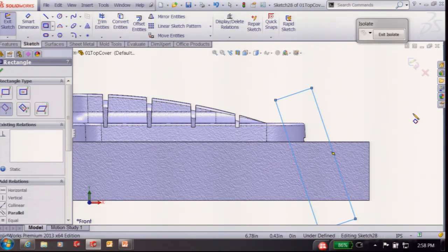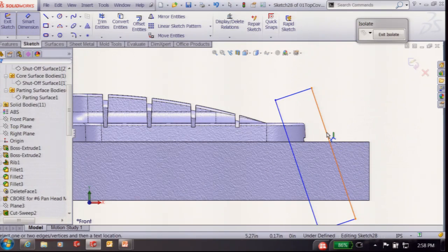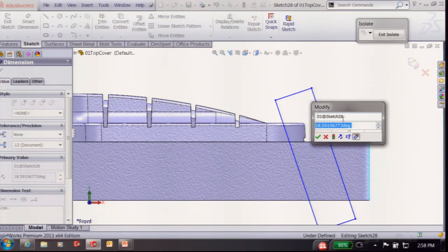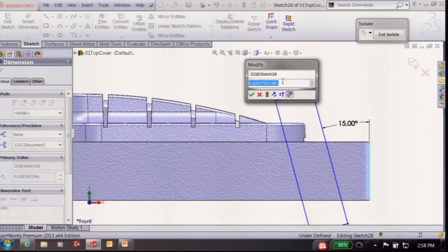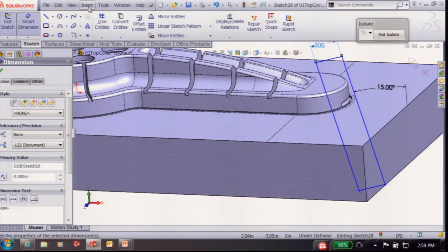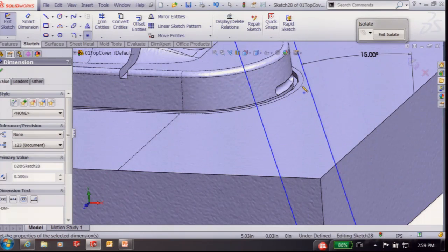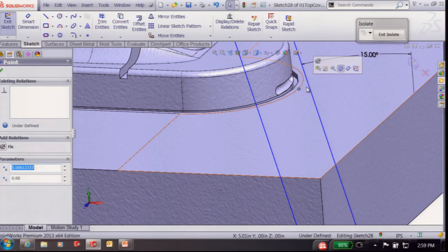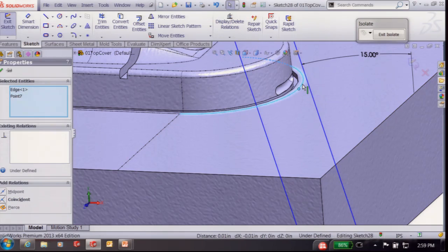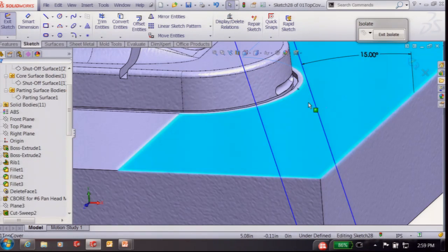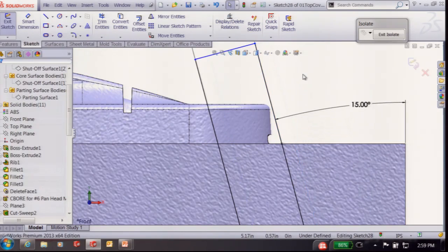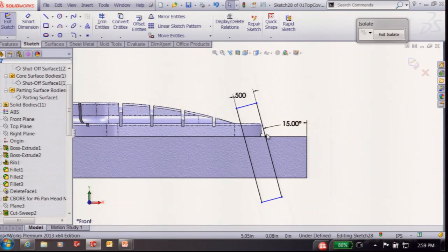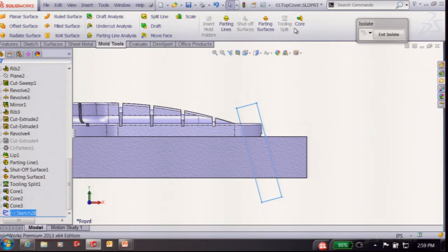So I got this angled, I can put this angled rectangle and define, you know, just give it an angle, maybe throw it in as a 1/2 inch. I'm going to constrain it because I have this little edge that it made around the side. I can constrain that point. I just did a point tool, make it a pierce relation, and then of course, let's go back to my view here. Make that coincident. And now I got my sketch here for my lifter pin.